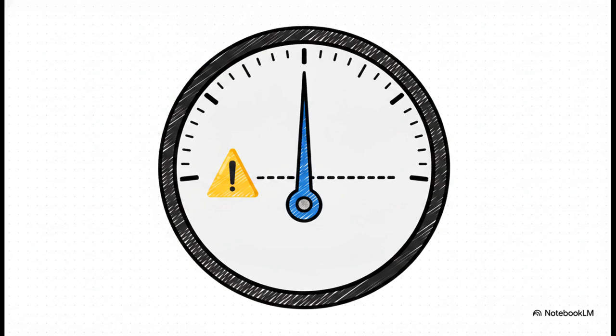But, and there is always a but, right? Check out the fatal flaw on the right side. Proportional control sounds totally logical, but it has a massive problem. It can literally never bring a system exactly to its set point. Why? Well, think of it like a giant puzzle. As your current temperature gets closer and closer to the target, the error obviously drops. And because the proportional term multiplies by the error, when that error drops near 0, the proportional output also drops to 0. So it just stops pushing entirely. As a result, the system always stabilizes just slightly short of the target. Engineers call this permanent gap steady-state error, or offset.